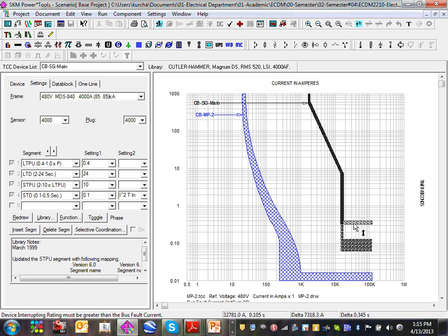Arc flash. Do you see the whole arc flash and your PPE? That component here at the bottom, that's responsible for your arc flash level. So let's reduce the arc flash level, guys, on the circuit breaker. If I move this way, less arc flash. If I move that other way, more arc flash. So these are a major part when you start dealing with the circuit breaker. Now I have a huge amount of arc flash. I moved it up, I delay it. You bring it down, it opens fast. You minimize the arc flash condition.